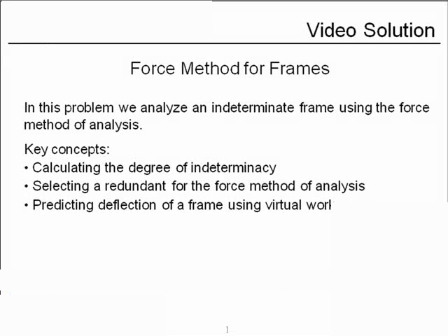The force method can be a very efficient way to analyze indeterminate frames if they only have 1 or 2 degrees of indeterminacy. So in this problem we're going to analyze an indeterminate frame using the force method of analysis. The key concepts we'll use are calculating the degree of indeterminacy, selecting a redundant for the force method of analysis, and predicting deflection of a frame using virtual work.